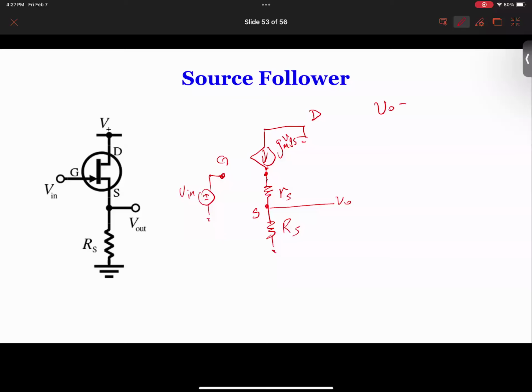So our V_O is equal to g_m V_GS times R_S. So this is V_O, and this is the current g_m times V_GS going down, multiplied by R_S, we get V_O. So we can calculate V_O, but of course, before calculating V_O, we need to calculate g_m for the DC biasing. Also, we need to know what V_GS is. But V_GS in this case is not V_in, so we have to look at what V_GS is. Basically, V_in is connected over at the gate.